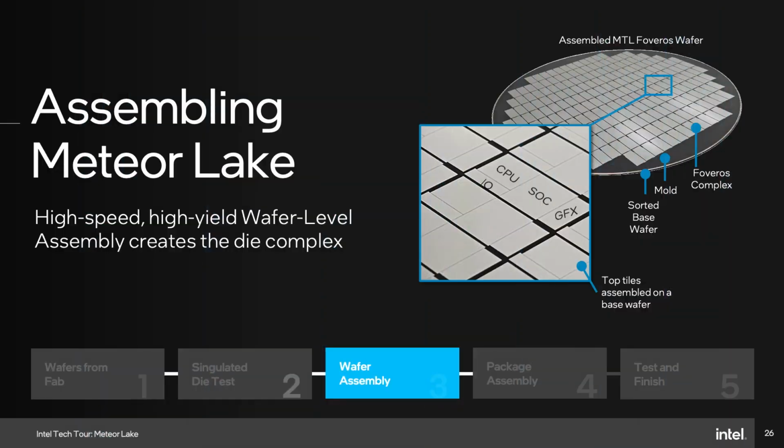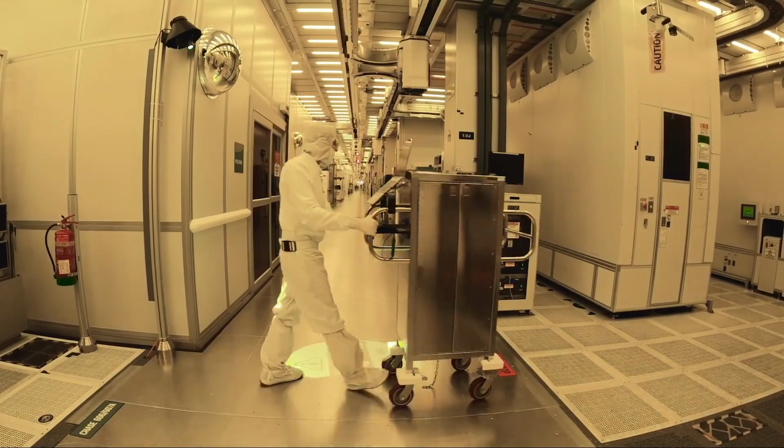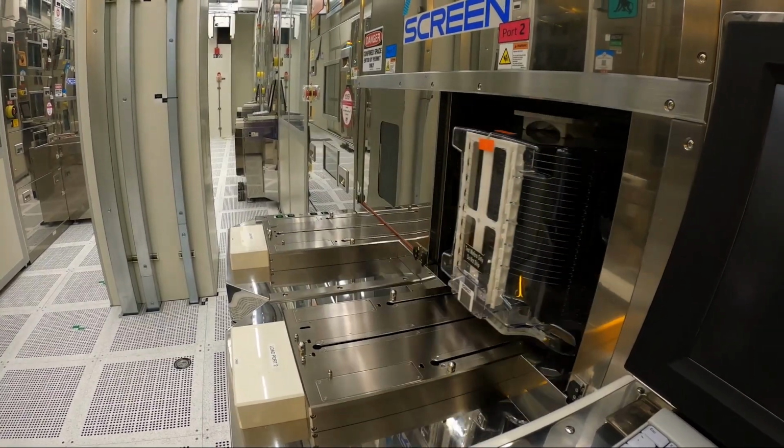After we sort them or singulated die test them, that's where we move to the first step of the Foveros operations. This is what we call wafer assembly. This was the major new capability that we had to put in. Obviously, we have to have tools, equipment, and processes to take the top die and stack them to the bottom die. So we do that. The bottom die or the base die is in wafer form when we do that. And the wafer assembly flow is unique in that it's a combination of both what we call classic assembly processes and classic fab processes.